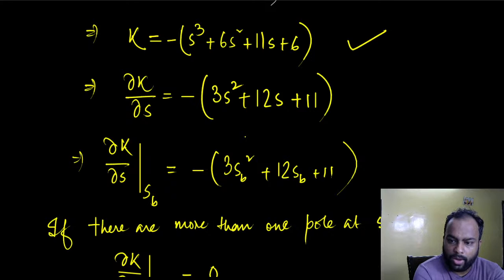Okay, someone is asking how we can check whether a system is stable or unstable if it's a difficulty 2, right? If it's a difficulty 2, proceed the way you do. If you encounter a difficulty 2, just create the auxiliary equation, construct the new modified row, replace the row where you encountered the difficulty 2, and proceed. And subsequently, if you have sign changes in the modified Routh table, then definitely you have poles on the right half plane. In that case, the system would be unstable.